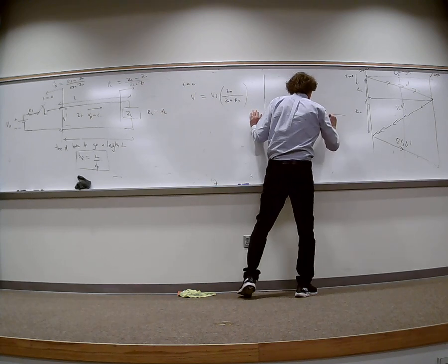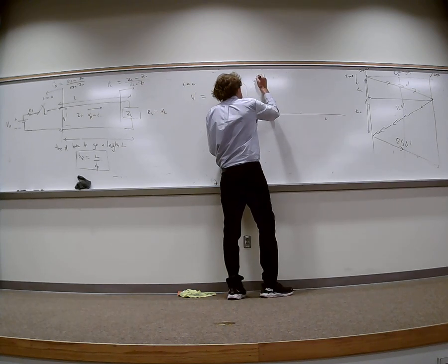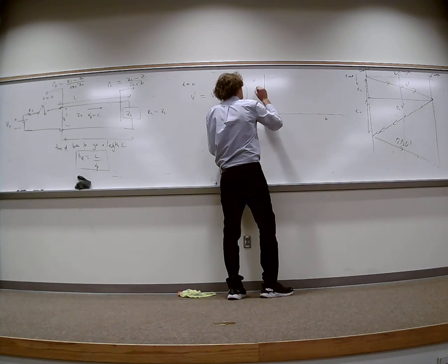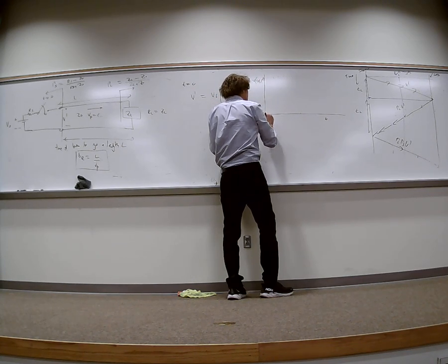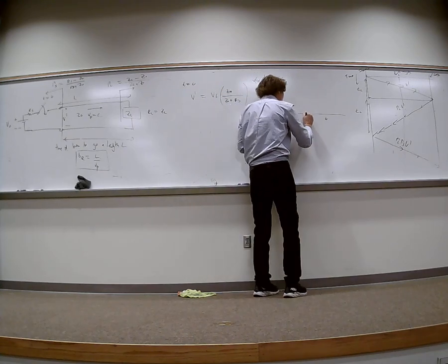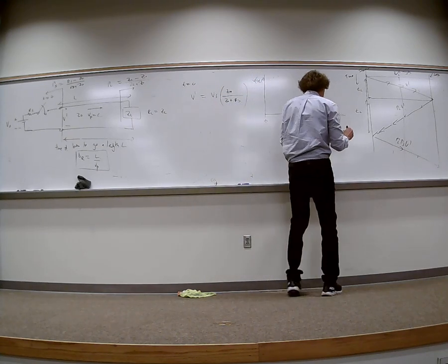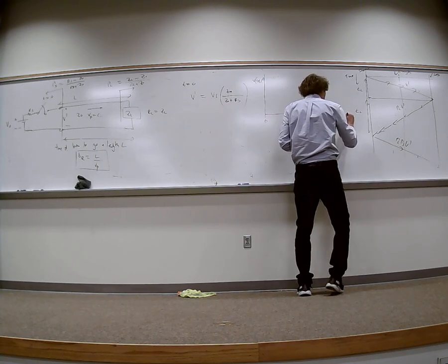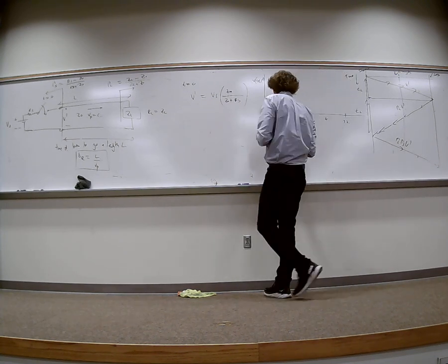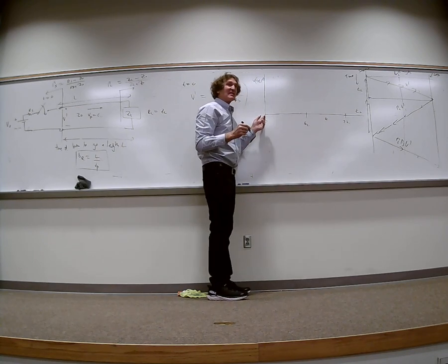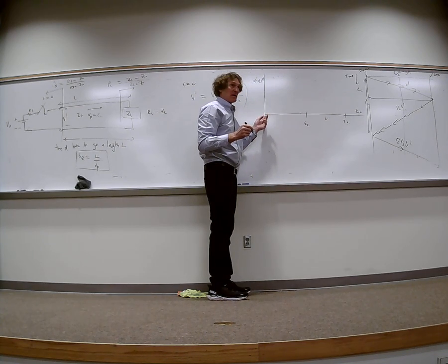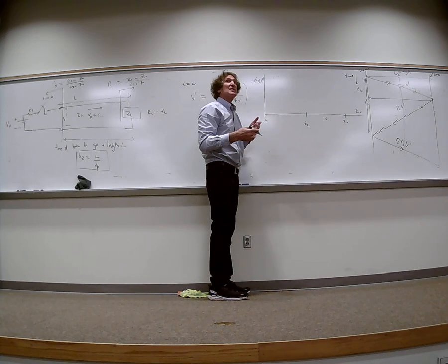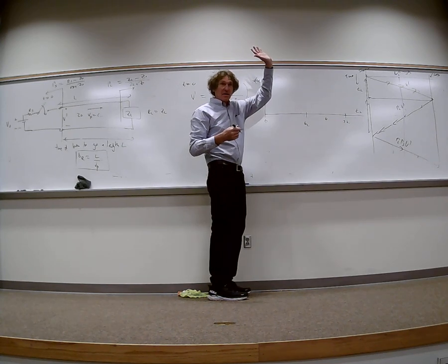And this is time, and this is the voltage that I'm going to actually measure, at the middle of the line. V at L over 2, comma T. This is 0. Now I know at TL, the wave has gone all the way down, 2TL here, and I'm going to keep going. So we know the voltage at the center is going to be 0 until the wave gets there, right? You all see it would be TL over 2 because it's halfway down? How many see that? All right?